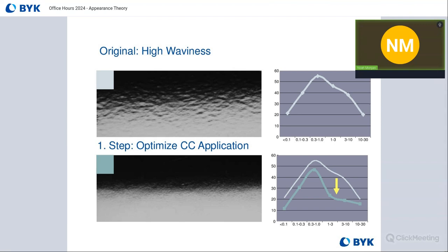So we see here some examples of the structure spectrums and what the surfaces actually look like. At the top example, we can say that's our original. It has a very not pleasing appearance. It's pretty rough and orange peel-like, very wavy too. And we see that our structure spectrum reflects this look. So we see that the short and long waves are pretty high across the board. The WC is very high as well. And it's not that 2-to-1-ish ratio that we'd really like to see.